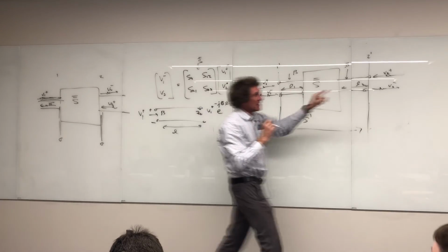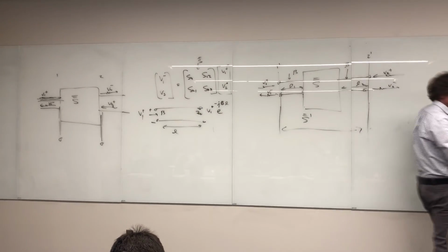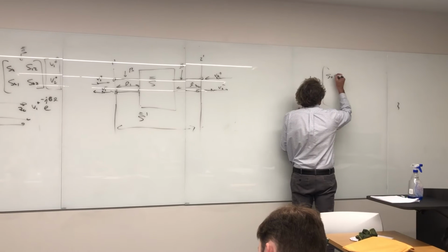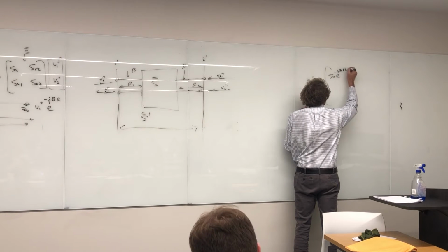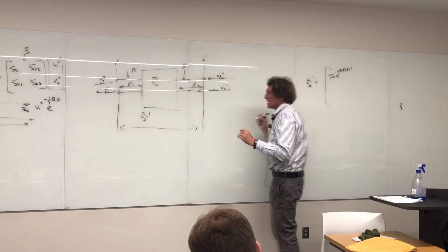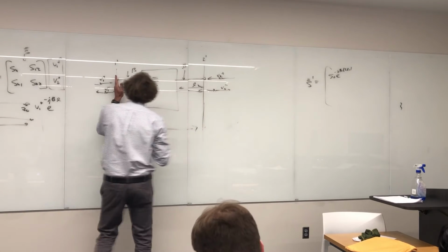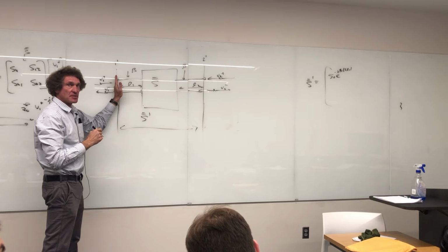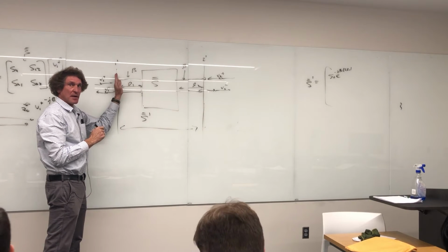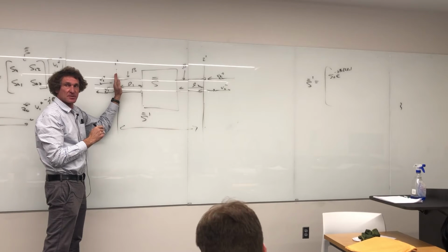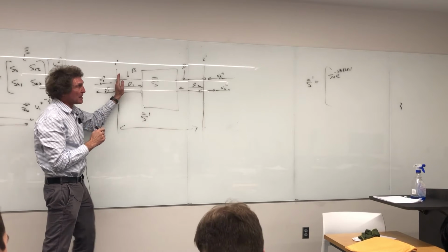So what happens right here, my S11, the original S11, is just going to be multiplied by e to the minus j beta, and it will be 2L1. And that will take care of this phase delay, because now the signal V1 has to move down here, has to hit port 1, and then reflect back. Does everybody follow me on this? It's not hard to see, but you have to be clear about this.